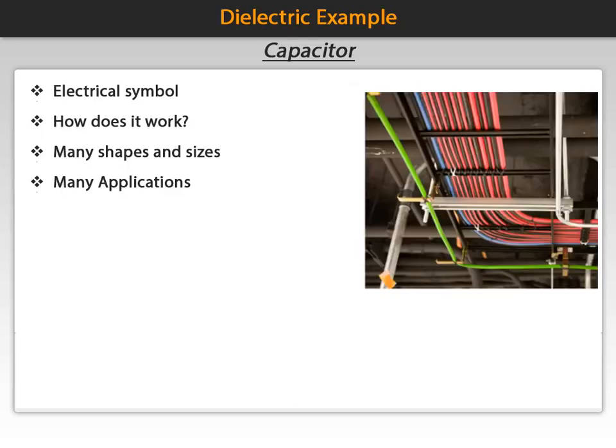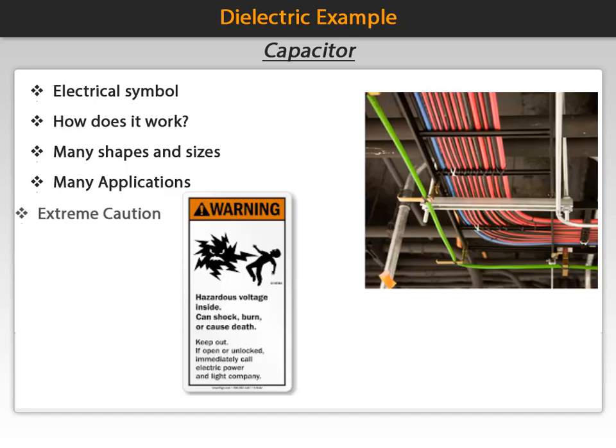Long runs of cable also have potential to store energy even though the power is switched off. Therefore, extreme caution must be taken when testing and troubleshooting equipment with capacitors and cable runs because of the ability to store energy.